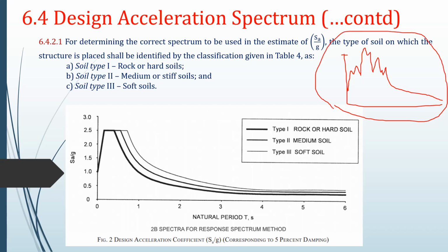And why is it inappropriate? It is because this irregularity is the characteristic of only one excitation. This spikiness, this irregularity of the response spectrum which we see for this one example, is only a characteristic of one excitation, and the response spectrum for another ground motion recorded at the same site during a different earthquake is also irregular.